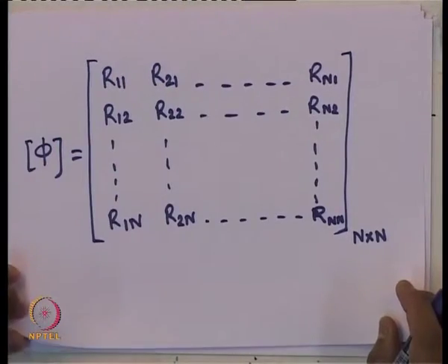Like this, using the transformation matrix, easily for any coordinate system, whatever equation of motion we got, if all the matrices are coupled or some of them are coupled and some uncoupled, we can transform them to our natural coordinate system, where we will get all matrices uncoupled or diagonal, and then we can solve it for the n degrees of freedom, which will be obtained from its natural frequencies, and then the corresponding solution can also easily be obtained.